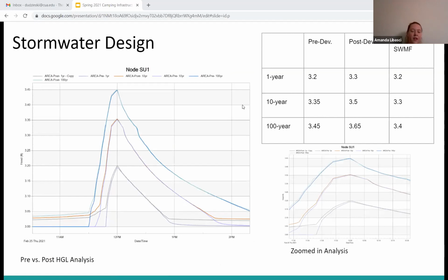The table above provides us with the pre, post, and post-stormwater design high groundwater levels, or HEAD, which shows the positive impact this bioretention bed will have on our site. In the table, you can see that from pre to post design, the water levels and therefore the potential for flooding increases. In the last column, however, with the addition to our stormwater design, those groundwater levels match the pre-development conditions, and in some storms will even improve the groundwater levels that currently exist.